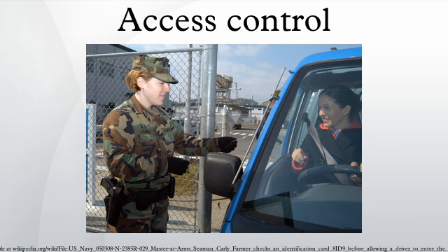Access control system operation. When a credential is presented to a reader, the reader sends the credential's information, usually a number, to a control panel, a highly reliable processor. The control panel compares the credential's number to an access control list, grants or denies the presented request, and sends a transaction log to a database. When access is denied based on the access control list, the door remains locked.